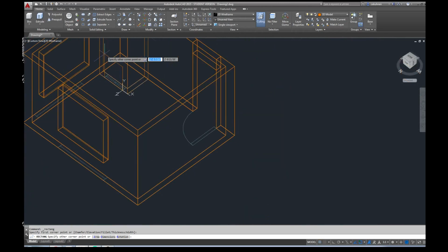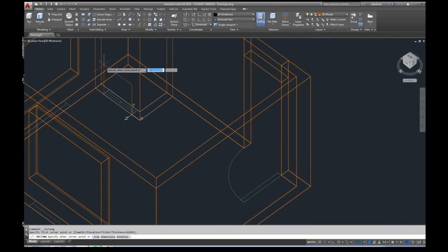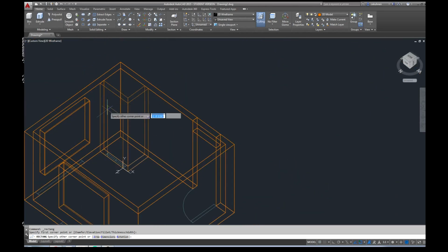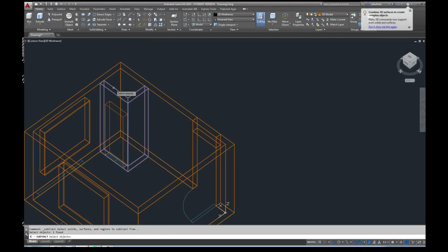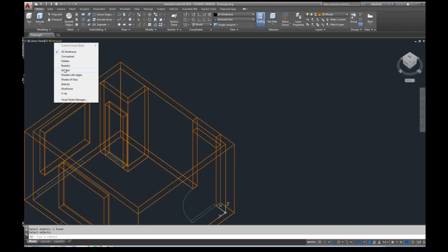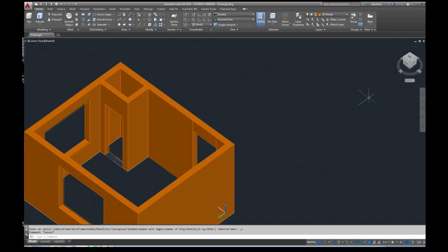There, I snapped to the point. Of course, oh, that's awesome. When you zoom in and out, then it loses that snap target there. And then I can go extrude, say U, spacebar, 6 inches this time. And then let's go to subtract, A, spacebar, B, spacebar. And let's take a look. There, it's cut out. Great.